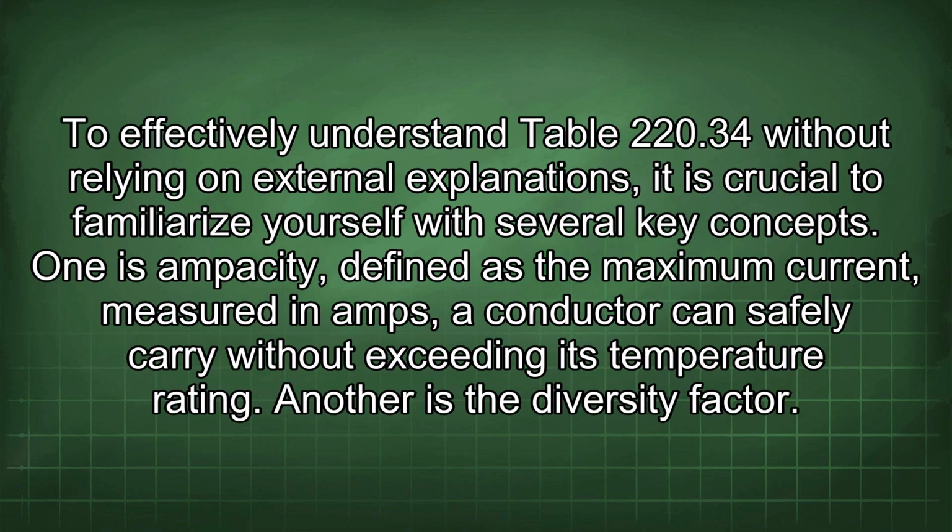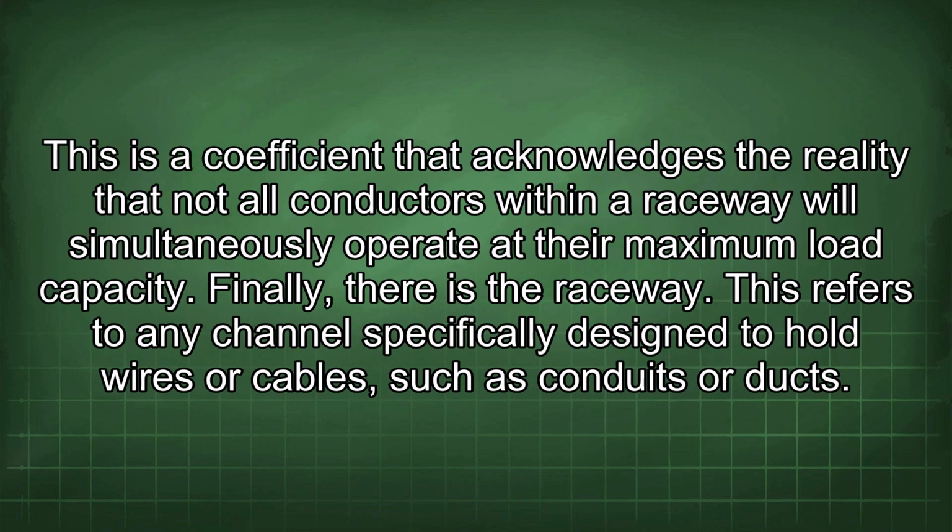To effectively understand Table 220.34 without relying on external explanations, it is crucial to familiarize yourself with several key concepts. One is ampacity, defined as the maximum current, measured in amps, a conductor can safely carry without exceeding its temperature rating. Another is the diversity factor. This is a coefficient that acknowledges the reality that not all conductors within a raceway will simultaneously operate at their maximum load capacity. Finally, there is the raceway. This refers to any channel specifically designed to hold wires or cables, such as conduits or ducts.